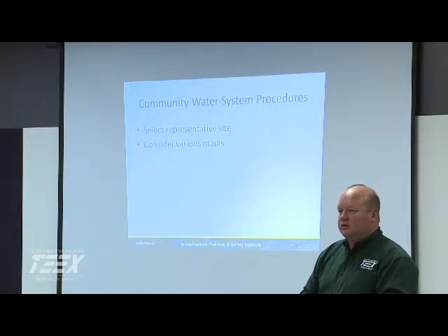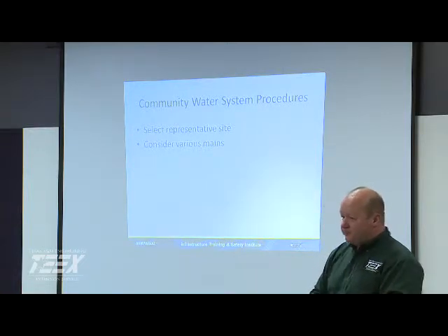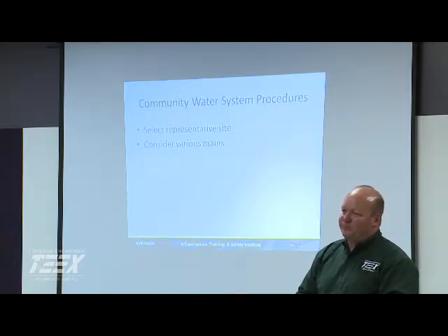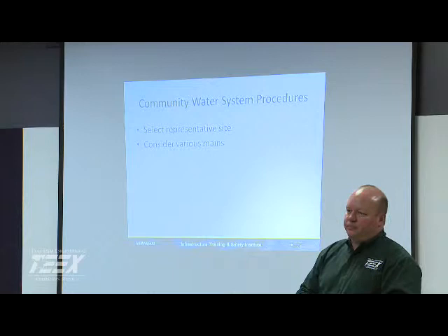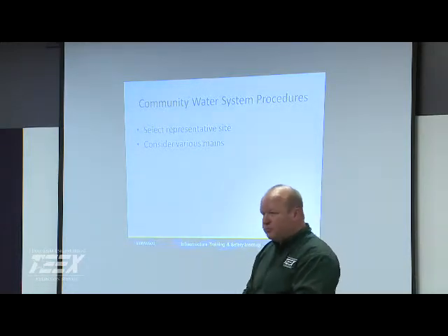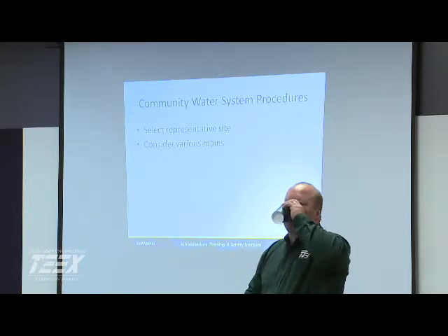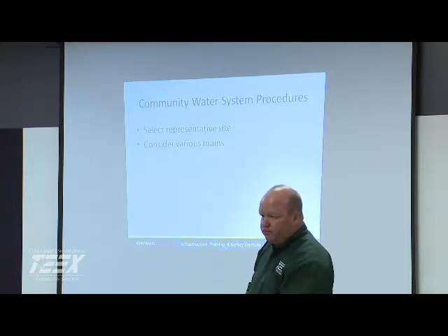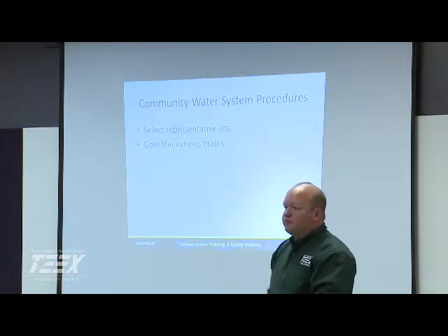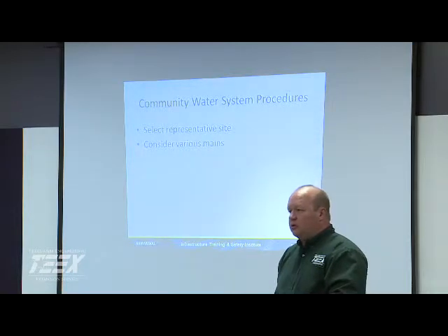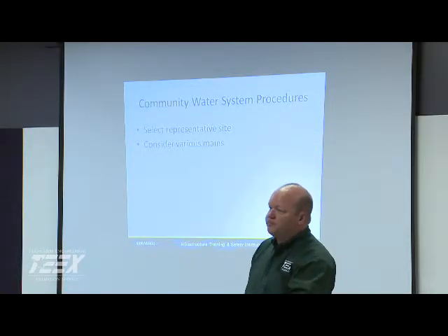We try to do maintenance on the valves, but it's hard. On the gas side it's a mandatory thing that you have to do every year, but on the water side I'd like to see it get that way. At the same time, having the manpower to be able to break loose and do it is another problem. That's what we're finding just everywhere. There's systems that want to do it, but they just don't have the manpower to get out there and have a regular valve exercise program.